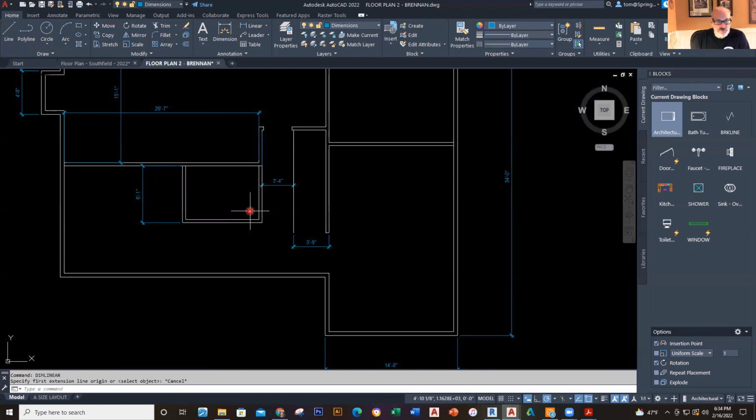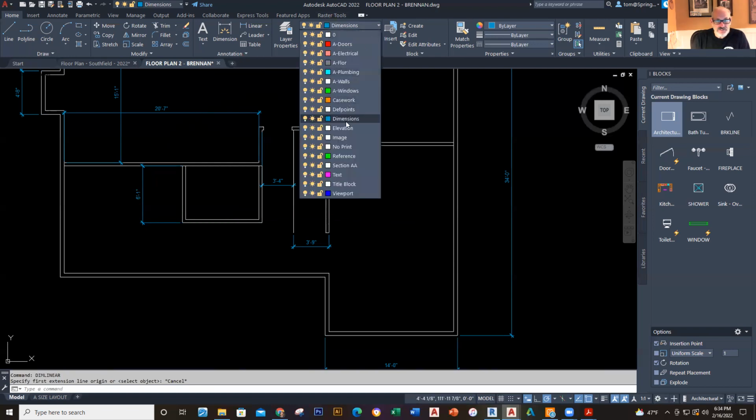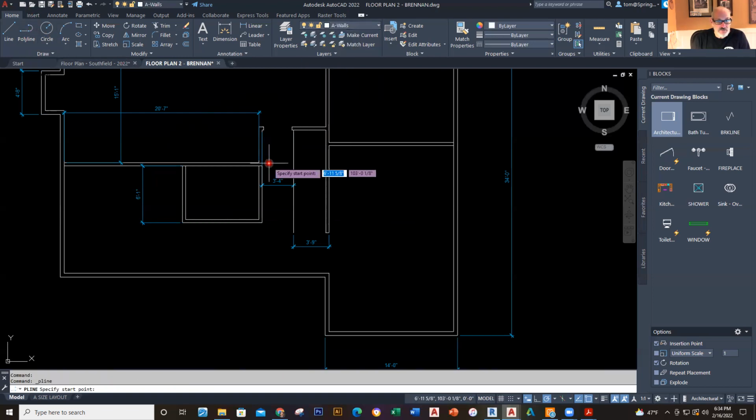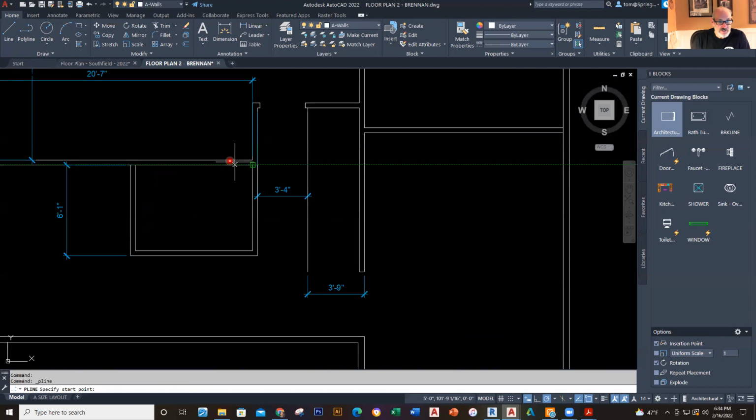I'm going to put in a 4'5" wall right here. That's got to be in here. So go here, and I will put in a 4'5" wall here, and go over 4'5" like this, and we'll pull it down like that. Okay, and then I'll offset that 4 inches over like this. There we go. So got that. And then I will offset that 2'9". So I'll just go down this line, 2'9".